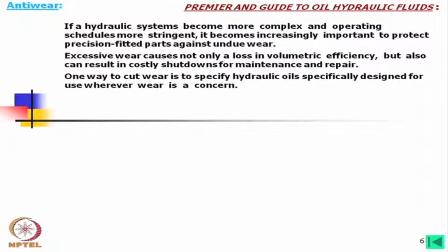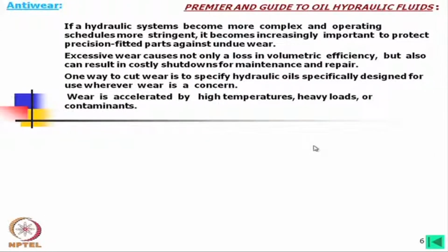One way to cut wear is to specify hydraulic oils specifically designed for use where wear is a concern. Now, I would say depending on the operations and the machines, there are different grades of hydraulic oils which can be selected. Wear is accelerated by high temperatures, heavy loads or contaminants.